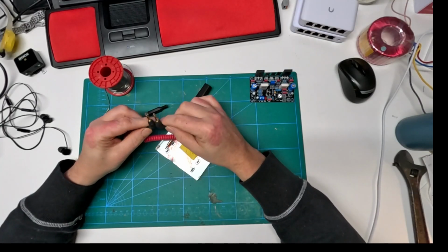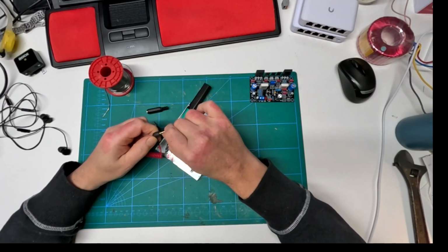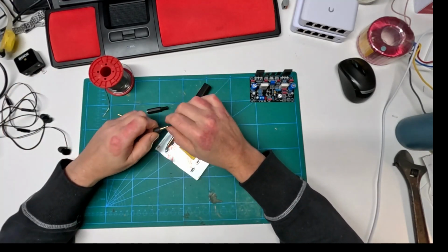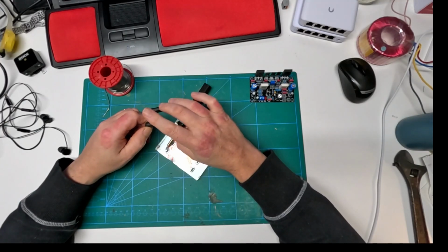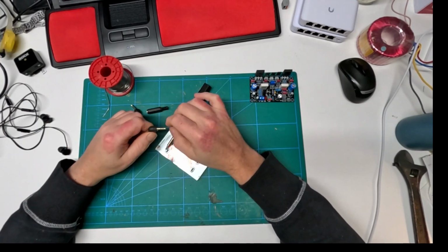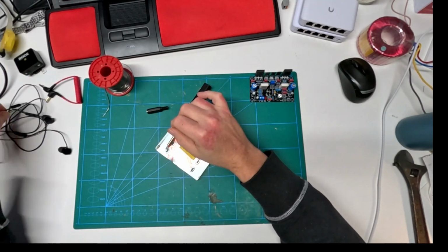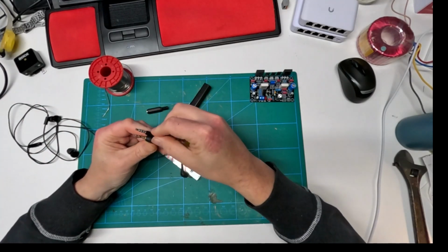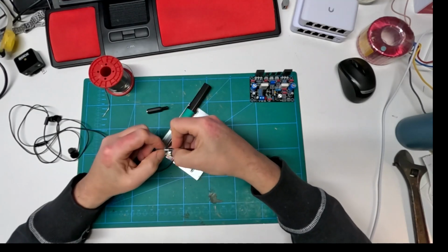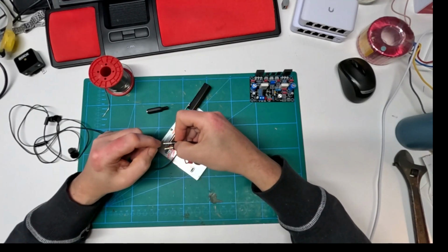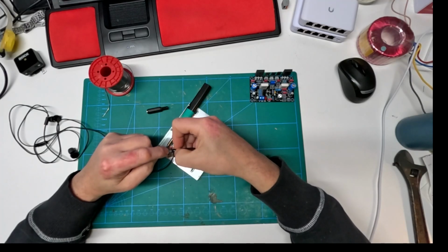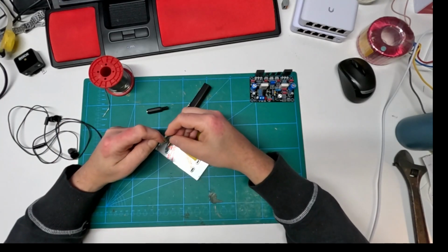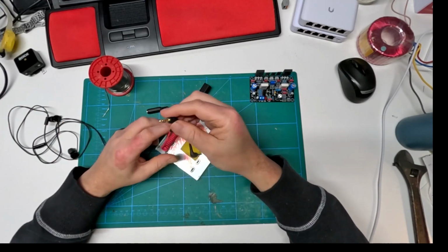kind of jack, and this is not the kind where you have the microphone input on the end as you have on modern computers. If you have an old-fashioned computer with its own microphone inlet, then this would have been okay, but I'm missing this fourth contact here. So if we have these along here, you can see this stripe here that is the break between ground and the microphone input. So when I plug this into an ordinary jack, the microphone input is grounded.